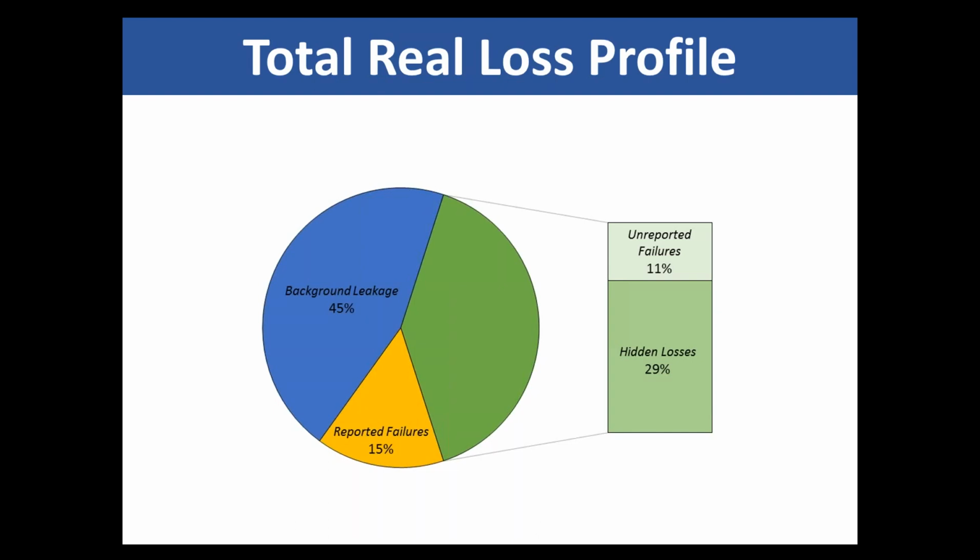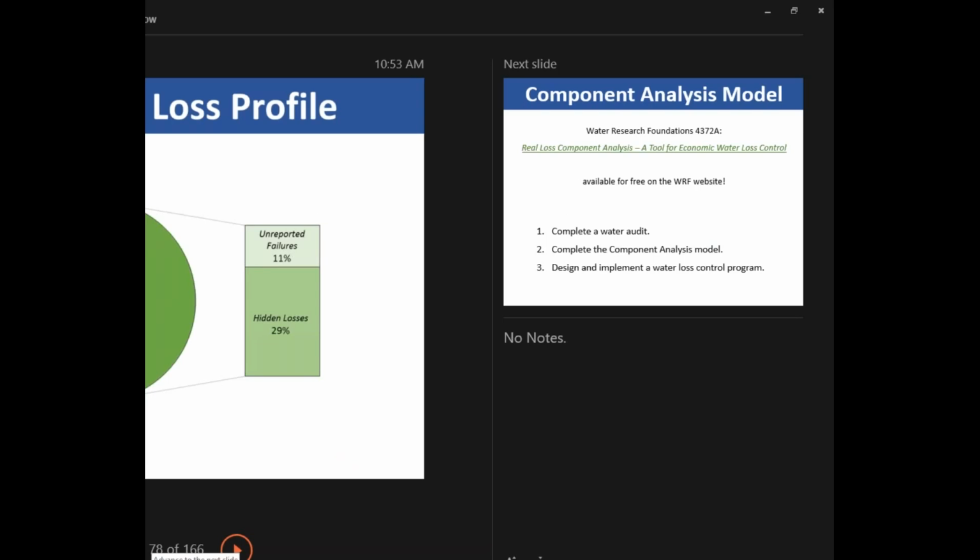And that sort of thing, if you see a scenario wherein what you're doing isn't mapping onto the results you'd like in terms of leak detection, it could also be a function of geography. It could be that the parts of the system that they're surveying more frequently aren't the parts that are leaking more frequently. And that sort of information you can gather with multiple phases of leak detection, but also with sectorizing your system. And as we talk about advanced management for water loss control, that'll come up, this concept of district metered areas, or discrete zones, wherein you can create a water balance on a smaller scale, a little bit more localized, so that when you go out to do leak detection, you don't have to do your whole system all the time in order to get your leaks. You can actually pinpoint them in their location a little bit more exactly and attend to them faster.